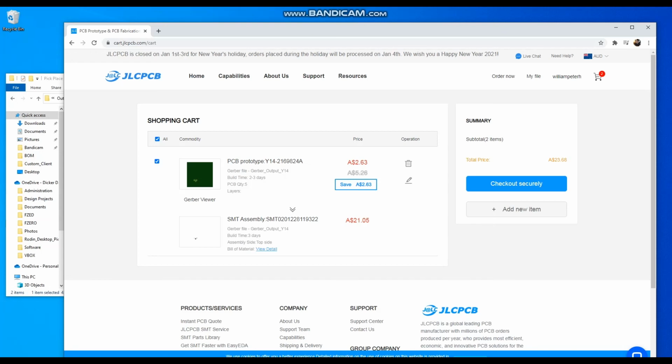And yeah, hopefully this tutorial has been helpful. I just made one because I didn't find anyone else showing how to get the JLCPCB assembly component schematics and PCB footprints, and make it compatible, so you can actually export designs from Altium and CircuitStudio, which are more common and robust design tools over EasyEDA, and use the JLCPCB assembly process, because it is quite cheap.